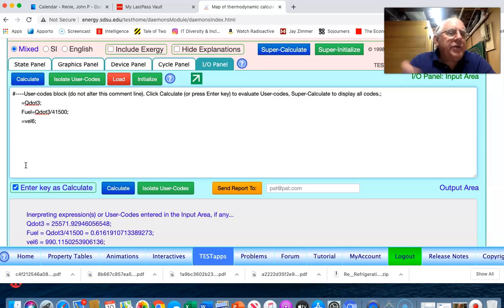And so now we're ready to calculate the thrust. And the thrust of the engine, as defined, is just really the difference in the momentum. And so we have m dot 1, which is the mass flow rate of air, and that m dot 1 now is just times the difference in the two velocities, velocity 6 minus velocity 1. Velocity 1 was the original velocity of the air coming in.